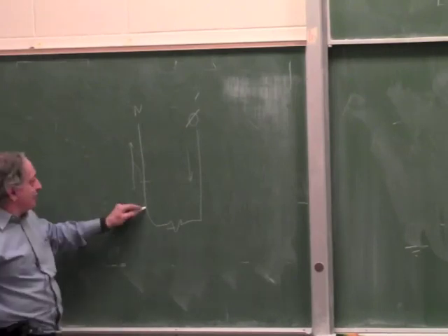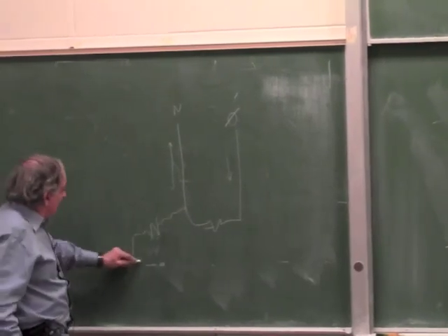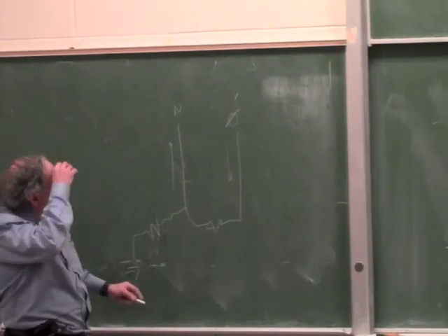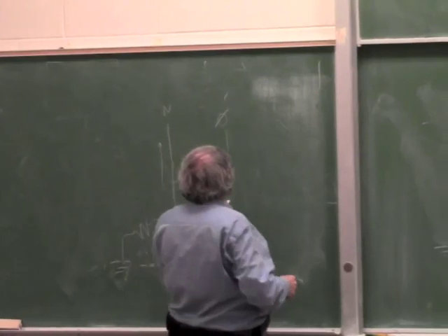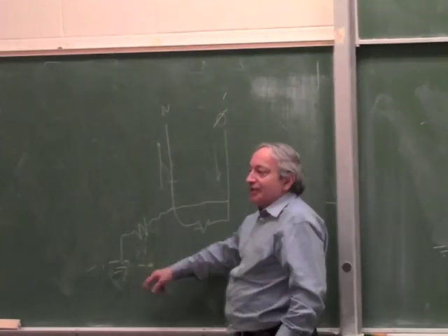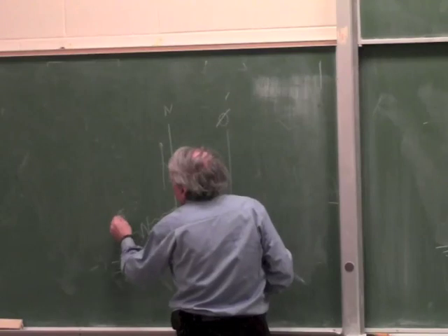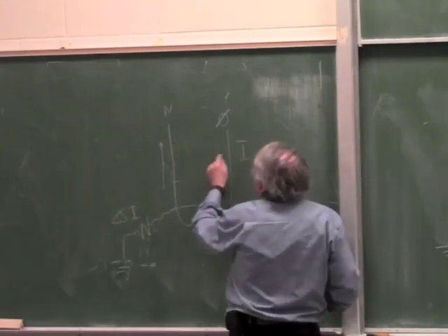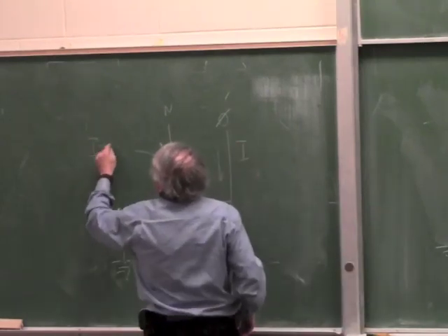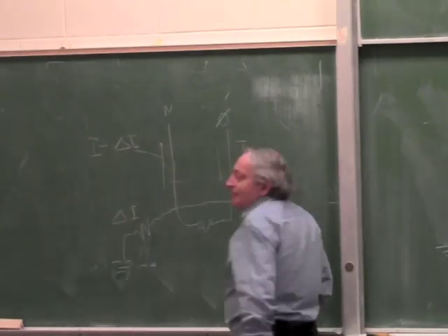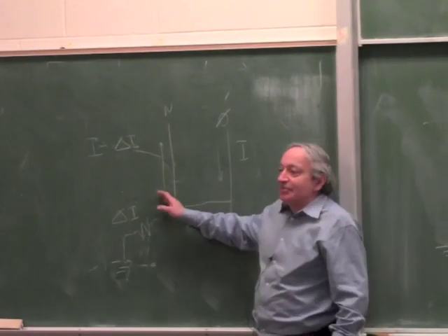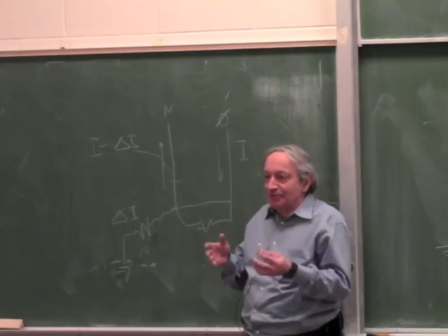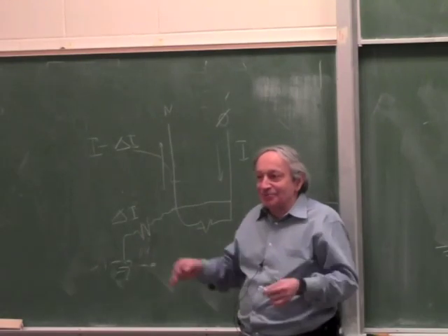Now if you get electrocuted, there is some current flowing to ground. Okay? So if some current is flowing to ground, I should draw it on the live side here. If some current is flowing to ground, and let's call this delta I, could be small, could be milliamps, then if this is I, the return current will be I minus delta I. Okay, so if these currents are not exactly the same, somebody is being electrocuted, or there is leakage to ground in the appliance, which is also bad. Shouldn't be used in bathrooms.